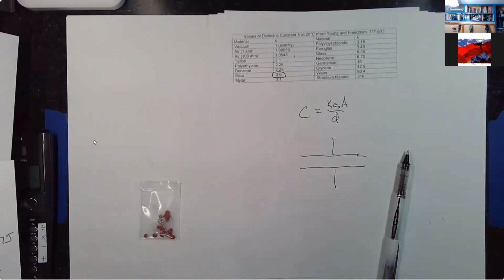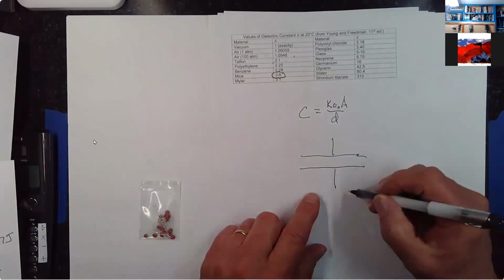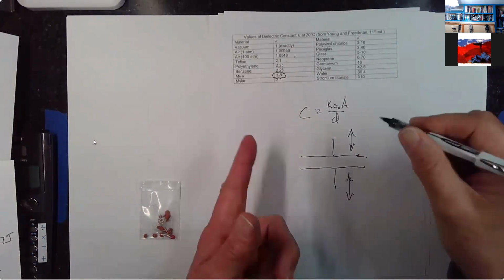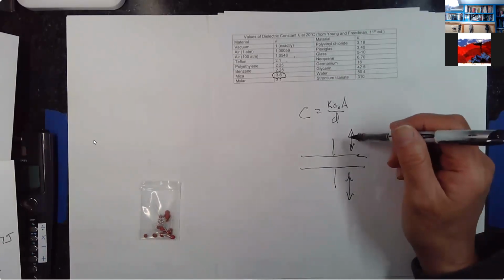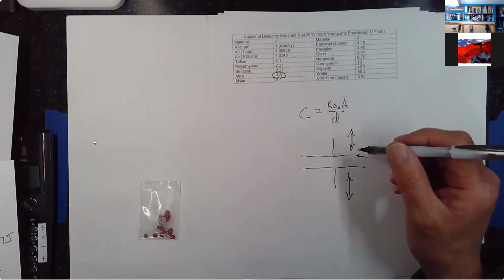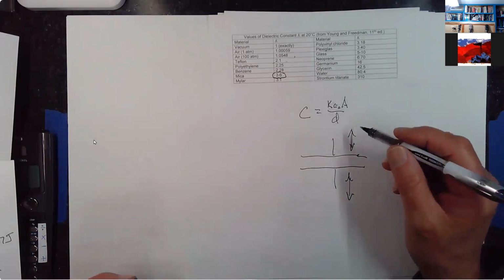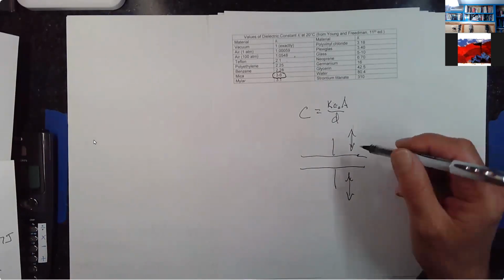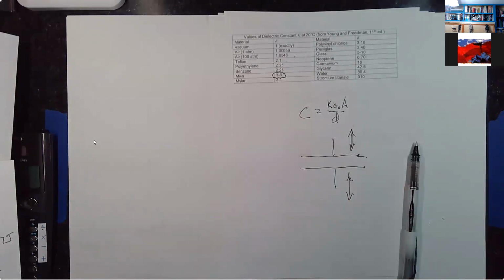The alternating current can still do its thing. Alternating current goes one way for a while and then the other way for a while, and it'll be doing that on both sides of the capacitor, which basically means you're building up charge on the capacitor and taking it off again. For alternating current, they can behave kind of nicely, but direct current will not get through the thing, and so it'll completely block that.